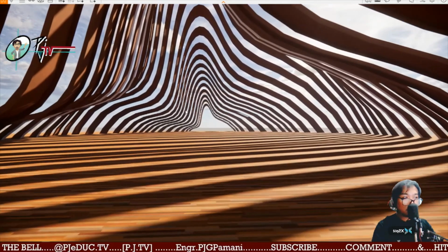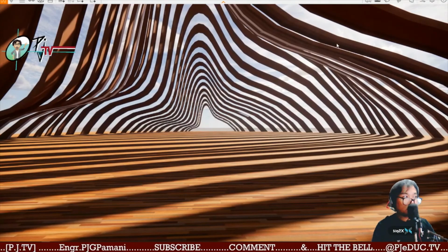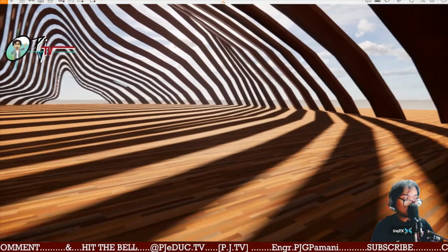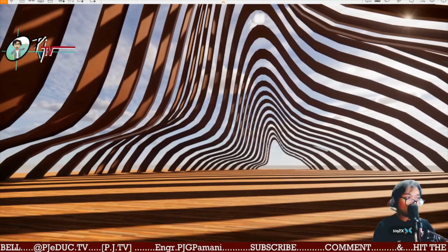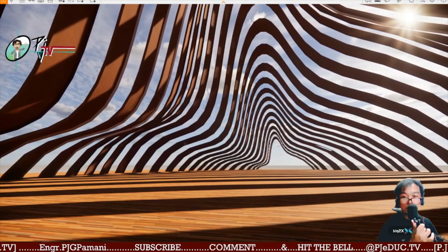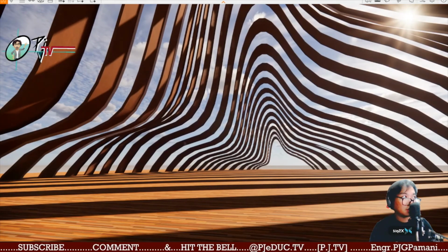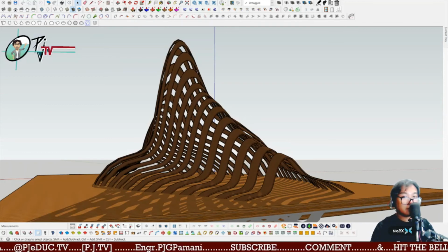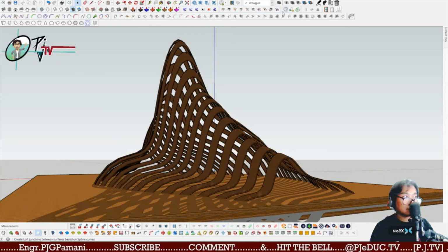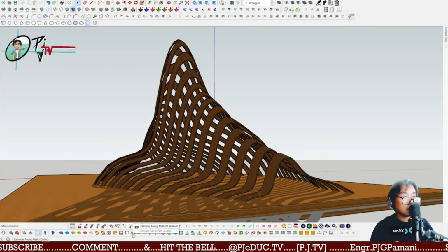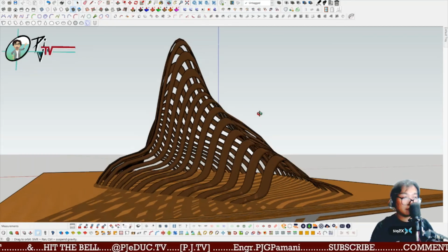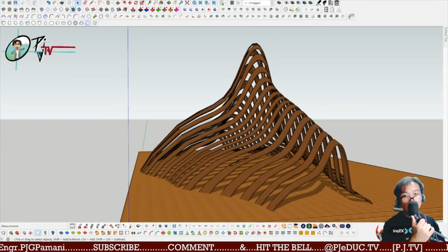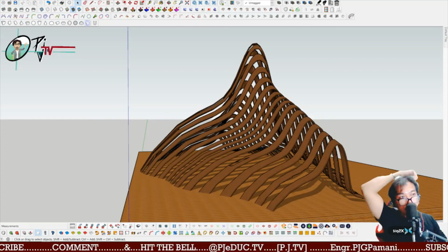If you want, you may remove those spaces between them and replace them with a glass object. That is up to you. It's just for the speed. Okay, so that is how you create an organic model using SketchUp extensions. Remember, what we have used here are the Joint Push-Pull from Fredo, we have Bezier, and we have also used Curviloft. And you may want to use the JHS power bar to divide your sections. So that is how we make an organic model using SketchUp and other extensions.